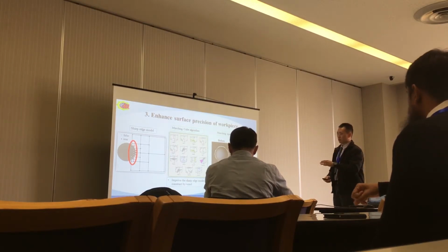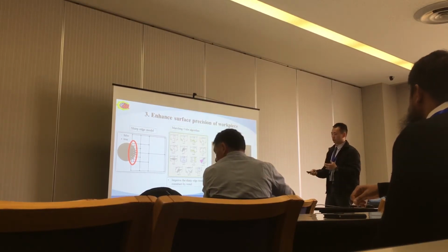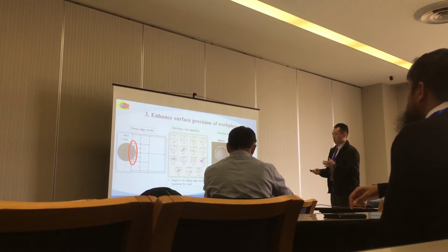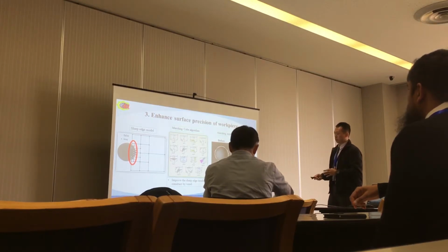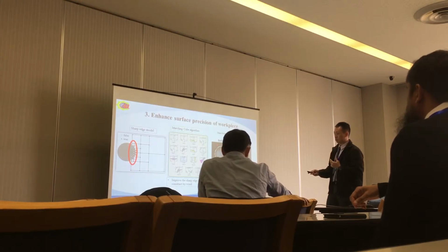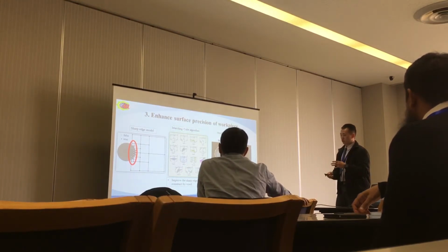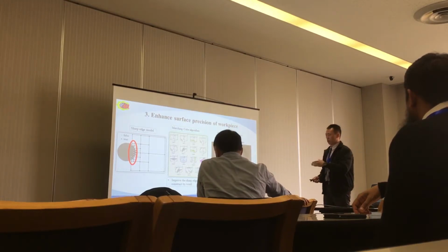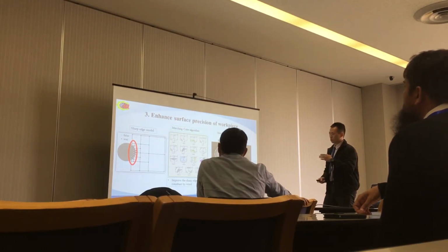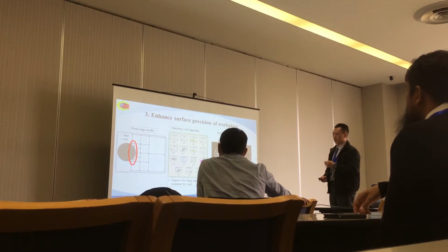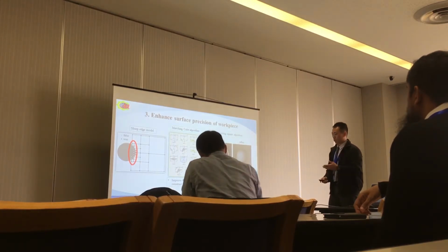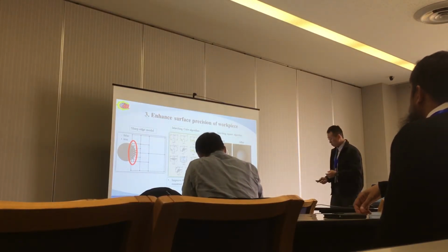After we construct our triangle isosurface, there will be a gap between the rest of the workpiece and the triangle isosurface that we just built around the tool. In order to fix this problem, we will use the Marching Square algorithm. What Marching Square does is basically like Marching Cube, but it's more like a 2D version.